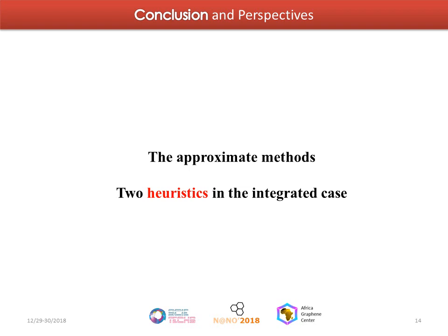This presentation addresses the problem of finding a robust and stable schedule for a single machine with availability constraints. The machine suffers random breakdowns and follows the Weibull function. The multi-objective function minimizes the robustness, stability, and the total energy consumption, which mainly include the energy consumption of machine tools and the common energy consumption. We plan to propose, in this perspective, resolution methods that will allow us to better take into account the maintenance aspects and also to solve bigger problems.